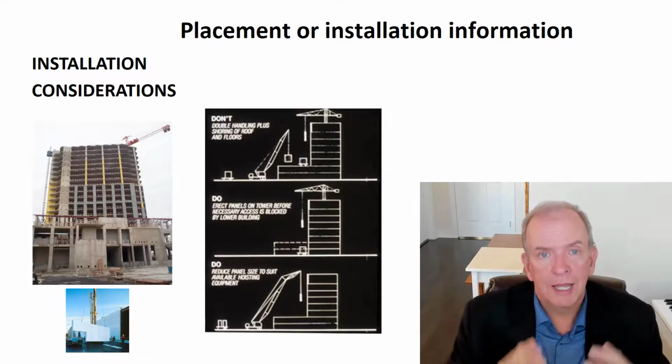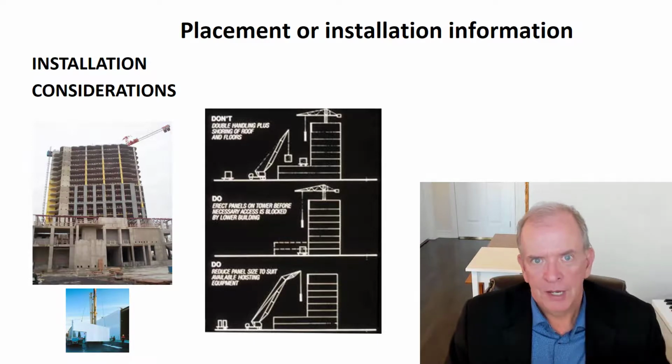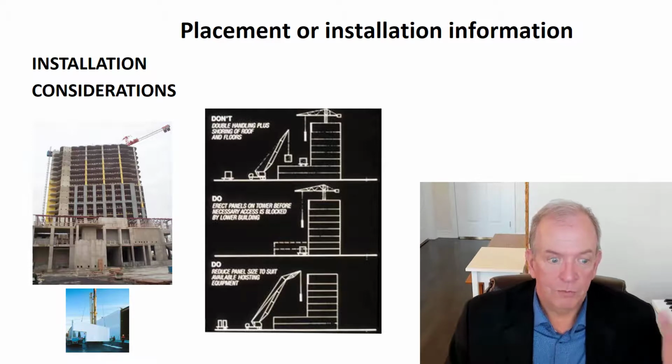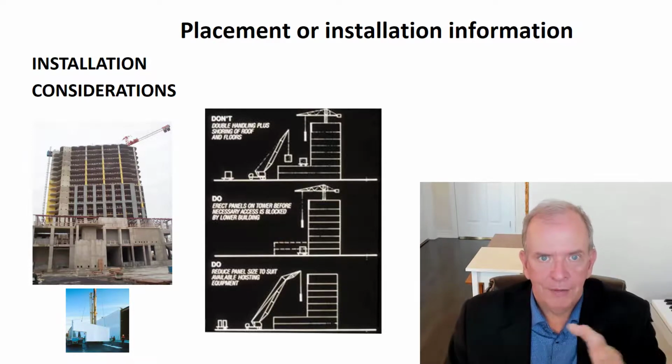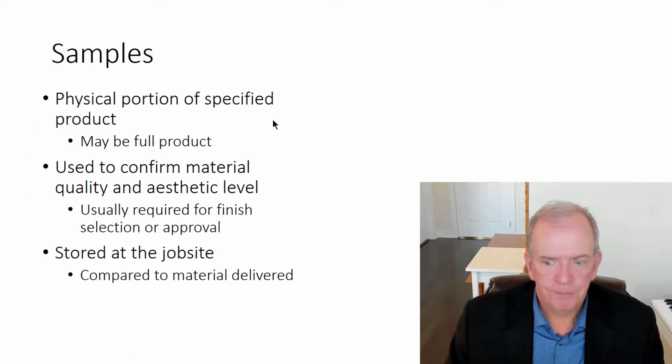You don't want something like that to end up slowing down the critical path of the project. You don't want to start not knowing where the anchors are to be placed. You don't want that to slow down the installation of your slabs and the pouring of the slabs and the superstructure, because that's on the critical path. And that'll just have a ripple effect through your whole project if you don't have that done.